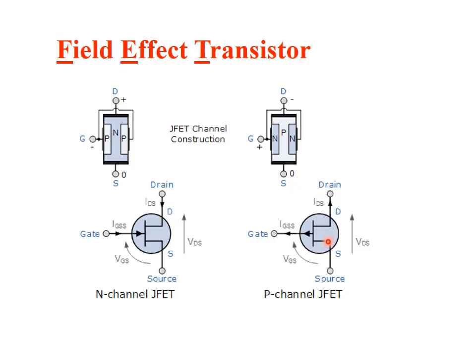And this is the circuit symbol for the P-channel JFET transistor. We will be focusing more on the N-channel JFET transistor. The only difference between the N-channel and the P-channel is the gate, and we will see the difference later. This one's gate needs negative voltage, while this one can be operated with a positive voltage.